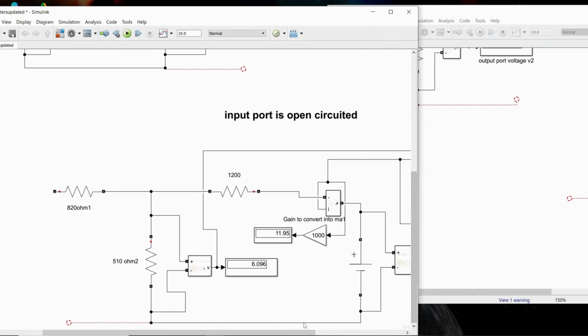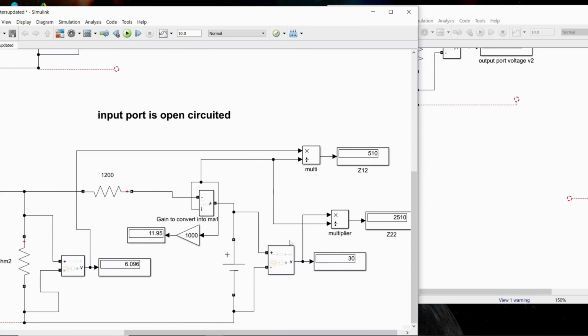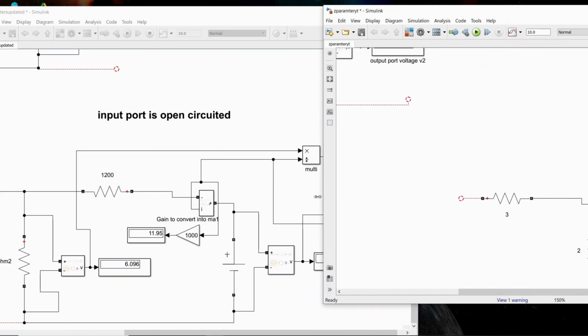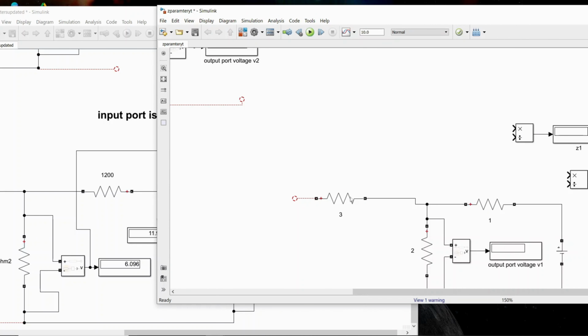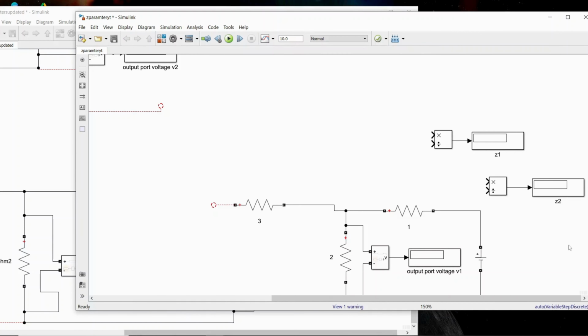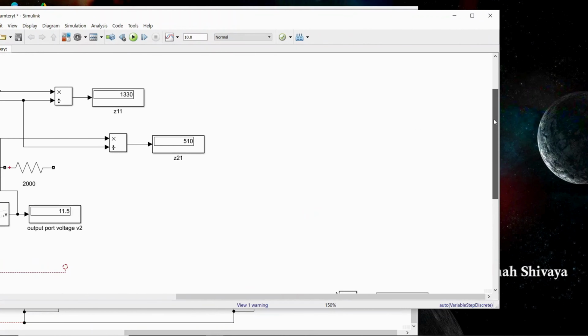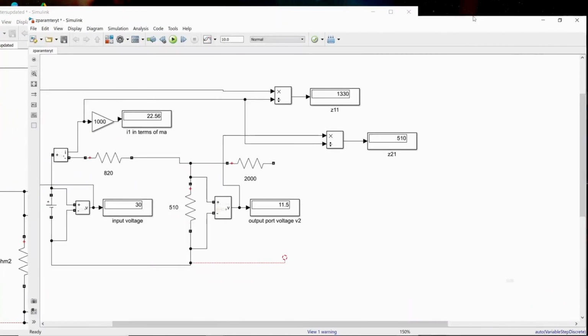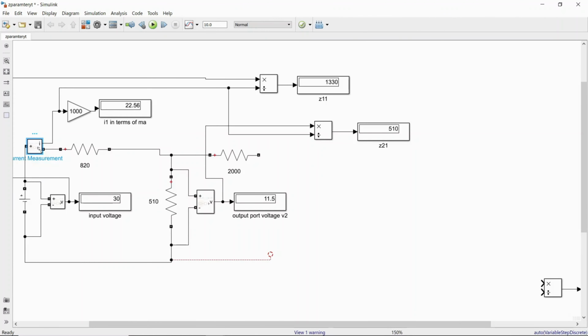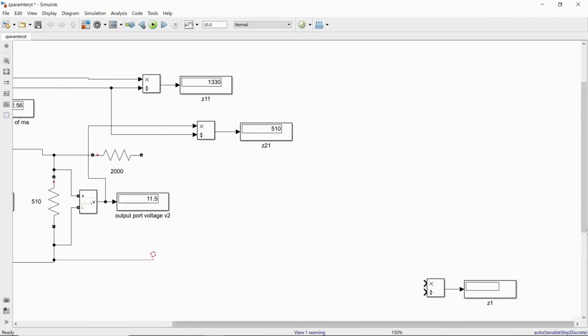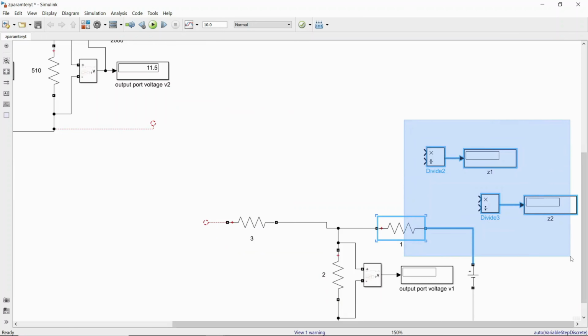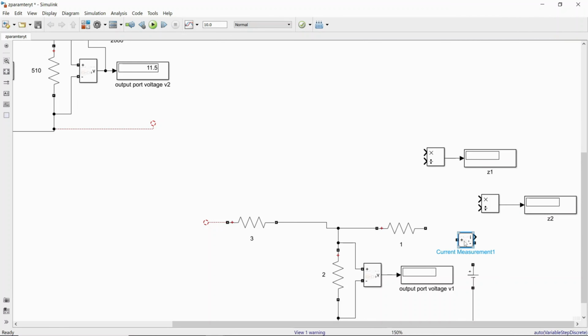So this is what we need for the simulation. We need to connect it. We require one voltmeter already connected, so just take the voltmeter and ammeter. At the output side you require the current, so you take the ammeter from the circuit. Copy the ammeter and place it here. Remove this connection and keep the ammeter. Just right click and paste, and rotate this.